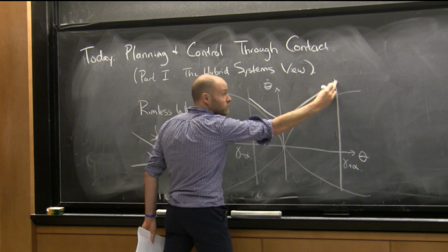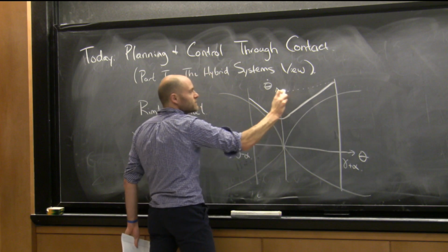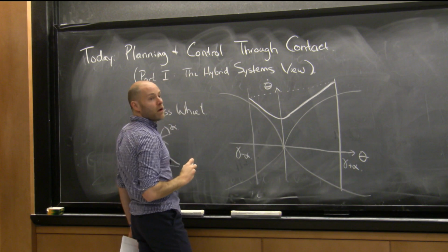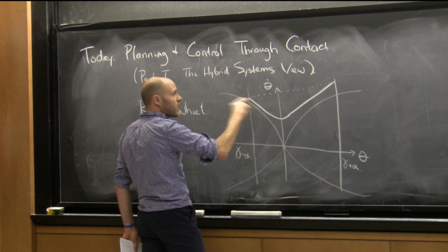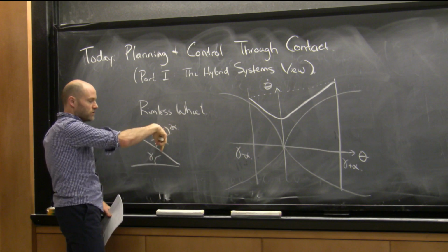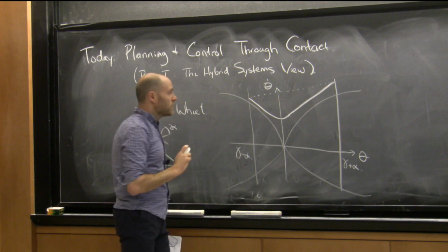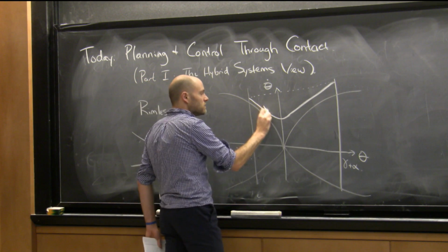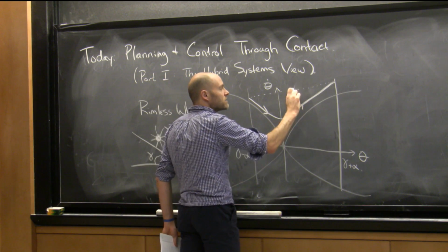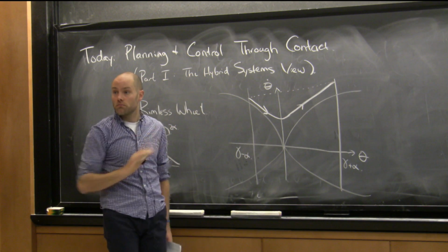So it leaves with more velocity, but it loses some velocity, cosine of 2 alpha, if you remember the derivation, as it slams into the ground. Then we rejigger the coordinate system so that theta is on the new foot, and effectively transition like this, and we have this stable limit cycle, where this is just the instantaneous impact that takes us back and resets the coordinate.